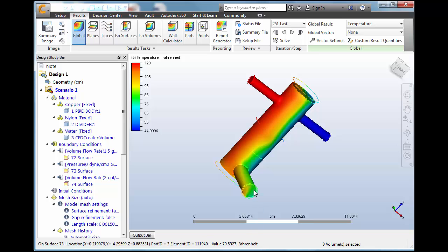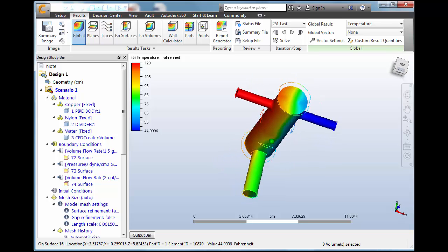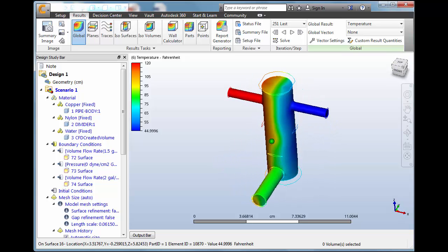So you can see that our outlet faucet pipe is going from the high 70 degrees Fahrenheit, nearly 80 degrees Fahrenheit. As we get over here to the higher temperatures, it's over 102. So this has a pretty wide range. That's about 20 degrees delta T in that outlet pipe. So we're definitely looking at making some kind of design change to this model.